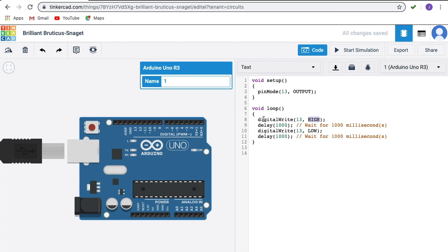Okay, after doing this, I want the LED to be turned on for 1 second. That is given over here. The value which we load here is in milliseconds. There is a function written in the library background, so we don't have to worry about calculating all the delay times. Just type delay and type how many milliseconds of delay you need and give it over here. After turning it on, it will wait for 1000 milliseconds. After that, it will come here and execute this.